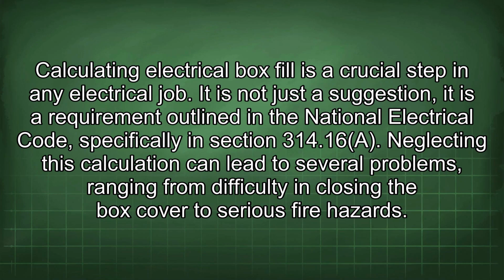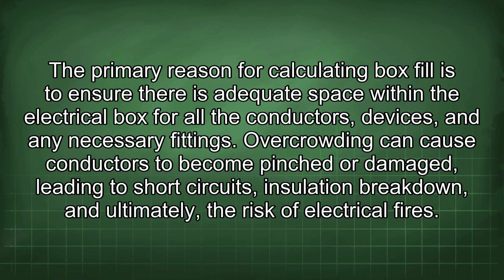Calculating electrical box fill is a crucial step in any electrical job. It is not just a suggestion, it is a requirement outlined in the National Electrical Code, specifically in Section 314.16(A). Neglecting this calculation can lead to several problems, ranging from difficulty in closing the box cover to serious fire hazards.